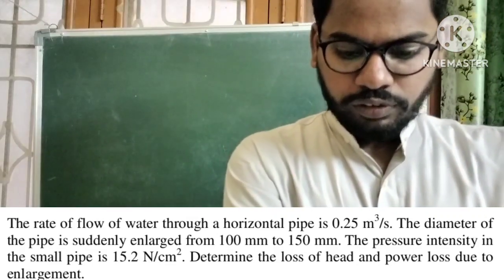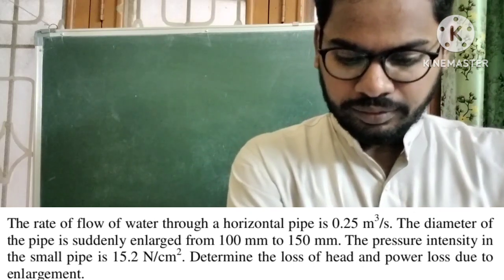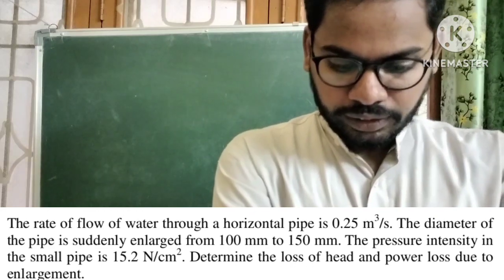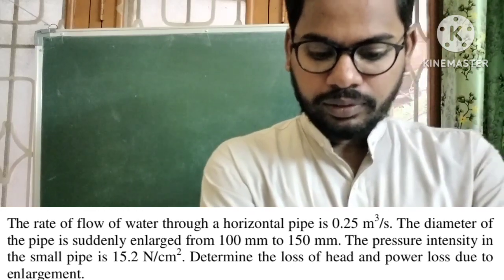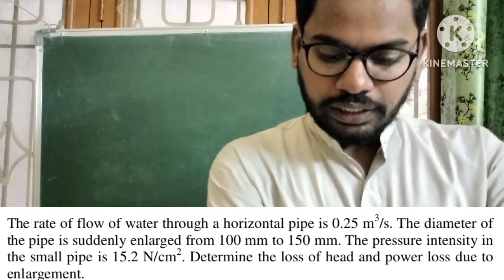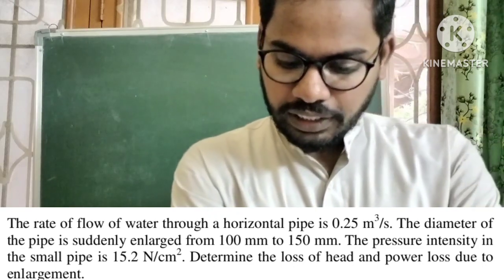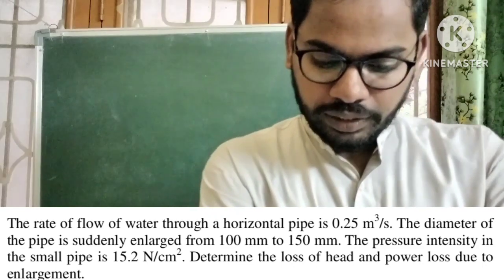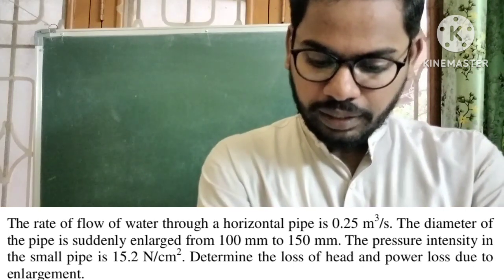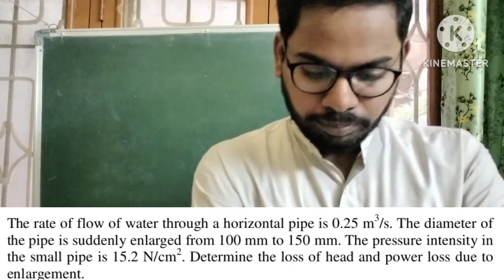The rate of flow of water through a horizontal pipe is 0.25 meter cube per second. The diameter of the pipe is suddenly enlarged from 100 mm to 150 mm. So there is a sudden expansion of the pipe. 100 mm to 150 mm. The pressure intensity in the small pipe is 15.2 Newton per centimeter square. Determine the loss of head and power loss due to enlargement.